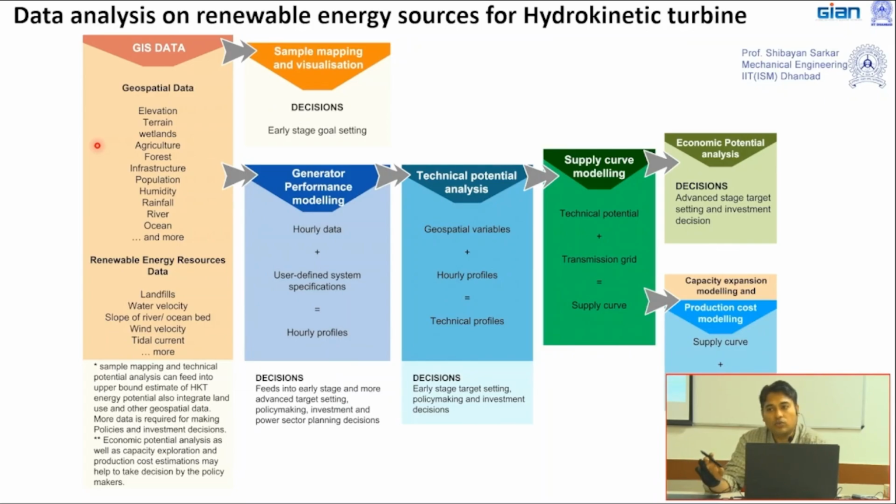There are different models which use these data to predict how much rainfall will occur in the near future maybe. If that kind of rainfall occurs in a particular catchment area, based on its shape, characteristics and land use, you can calculate how much discharge is available at a certain point of the river. So that exercise can be done, and GIS data will provide you that data.